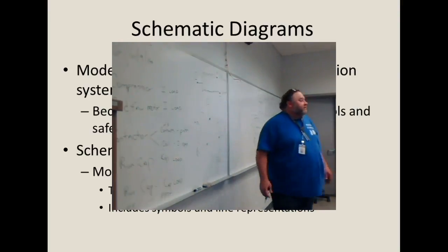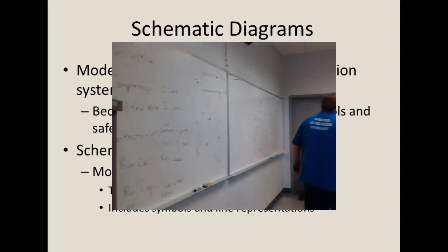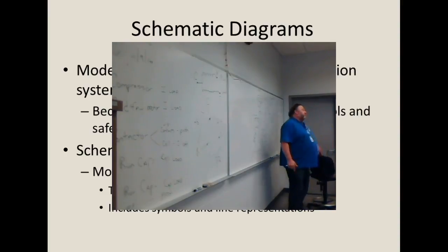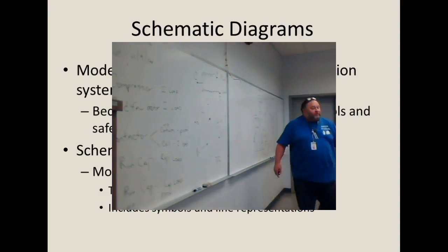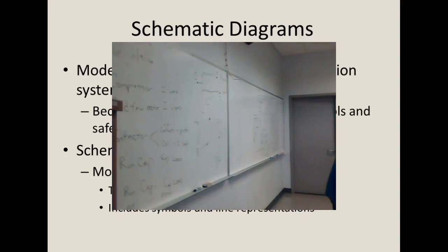Now, take a look at your lab that I gave you. Over here, on the other side, there's a bunch of compressors labeled A through, what does this go to, K? If you can't find one, then come to me and say, Clay, we can't find C. Probably means somebody ripped the paper off of it. We'll fix it. Just come tell me. But first of all, y'all see that? A through K? You're going to go to each one of those compressors and you're going to do what Terry just did. You're going to ohm them out.